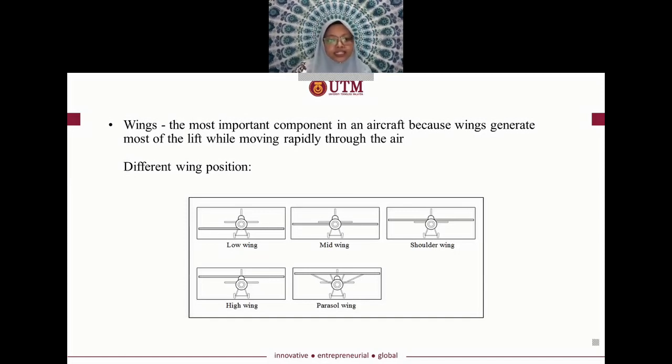A low wing is the type of aircraft that has wings positioned on or almost at the bottom of the fuselage. By locating the wing down low, it allows better visibility and releases the central fuselage from carrying the wing spar. While a mid-wing is positioned midway up the fuselage, it is now bound to carry the wing spar and hence reduces the useful fuselage volume near its CG, or center of gravity, where space is often in most demand.